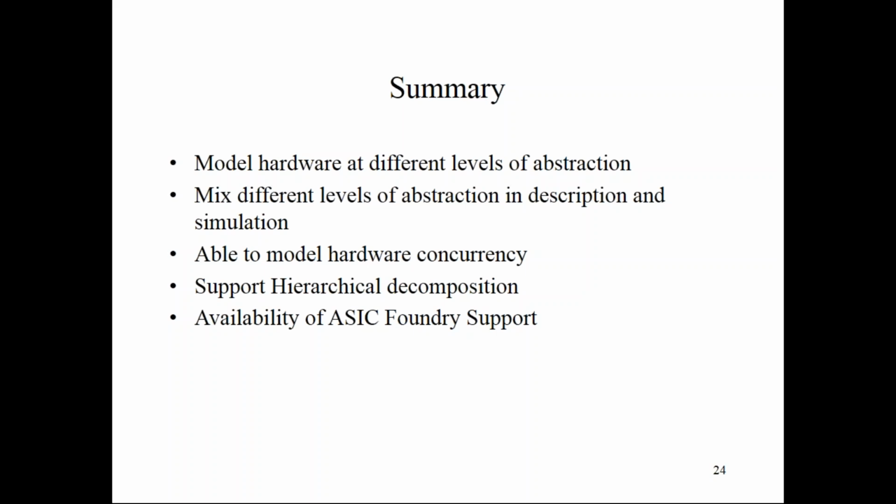And instead of initial, which is used for concurrently executing the input test vectors, we are always using an always statement inside the hardware element. That means an actual statement, because it defines how the output will change based on the input. That's what is actually defined inside the always statement.